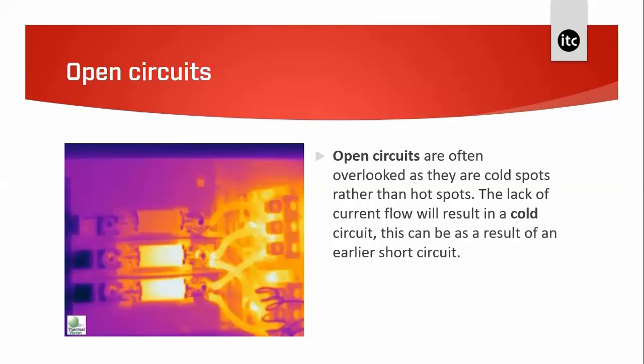And it can be the case that the fuse with no load is blown, and in some cases it can be on an item that may not be noticed readily by maintenance personnel. Just a note here, don't overlook a cold component on a circuit because it could be the major problem.